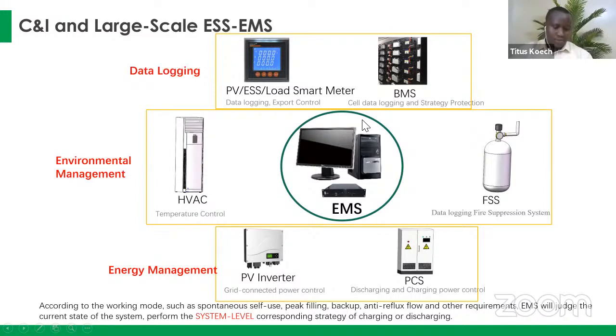Okay, we are actually almost done. So thank you, Monif. If you look into the C&I storage that is available with different technologies, we also require the energy management system. The energy management system performs different functions, from data logging, to being able to get data from either the batteries or from the loads, or also from PV in terms of the generation.